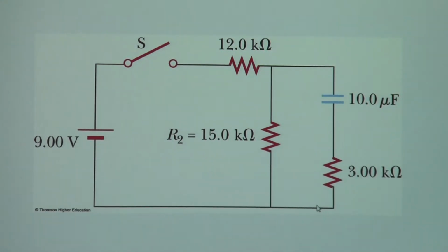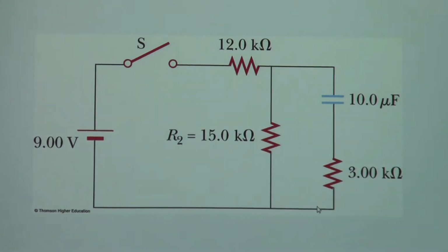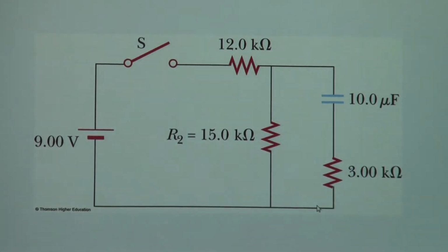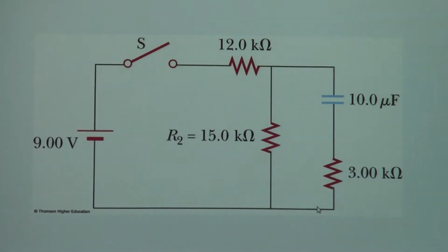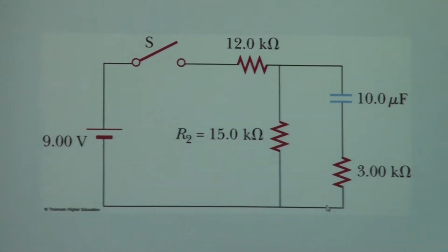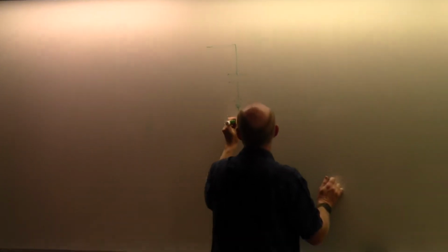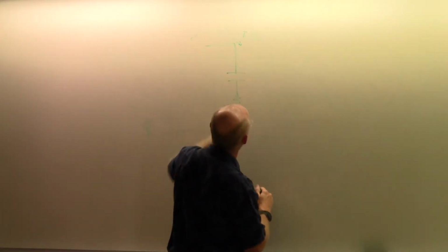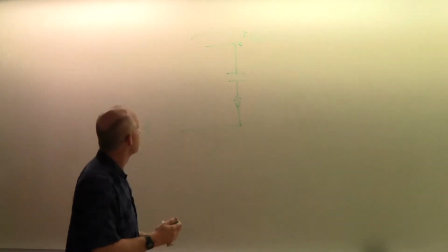So you're saying that the capacitor has voltage just by having no current, but the resistor doesn't? Yes. Remember, the resistor has voltage because the current is flowing through there, Ohm's law. The capacitor has voltage because charges have built up on it. So if I was just looking at that last part of the loop, current would be coming on here, okay?